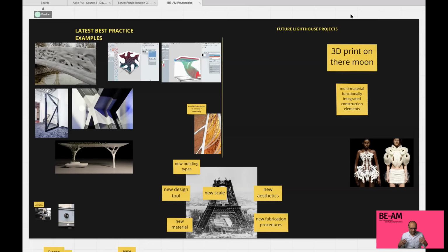There are very ugly objects at first glance, but maybe that means we have to get used to a different aesthetics. We see there are new tools coming up that treat geometry not as a surface representation, but as a volume broken down into voxels, and every voxel could have different properties. We see that things become competitive in terms of economy, like this 3D printed facade node that is almost comparable to if you would mill it.